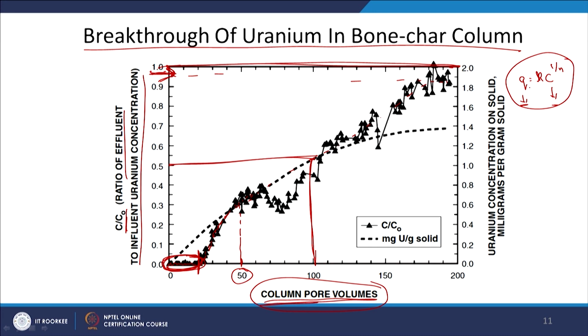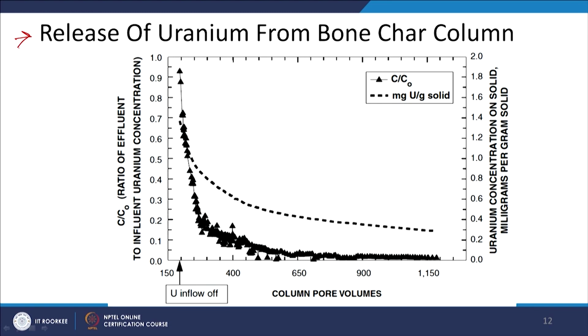So what is this giving me an idea about? It's giving me an idea about the equilibrium relationship between the concentration of contaminant on the solid phase and the concentration of contaminant in the aqueous phase. Again, some other aspects for you to understand here. The key aspect with adsorption, desorption, or precipitation and then release or dissolution is this: let's say I have groundwater and my PRB is out here, and the contaminated groundwater is flowing through. As it flows through, the relevant compound is adsorbed onto the material here, and now the groundwater leaving the system doesn't have uranium at high level, or has no uranium, okay. But what would happen when all the contaminated groundwater has passed through, and you now have uncontaminated groundwater coming in contact with your PRB material, which now has the contaminant adsorbed onto it?